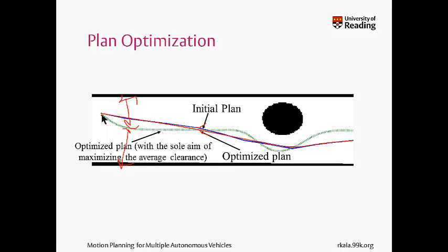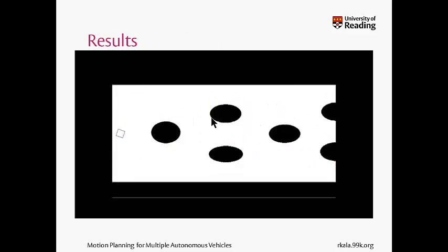So therefore, when the vehicle was here, this road boundary exerted a very big force on it. It exerted a very big force, and quickly it drives to the center. And after that, it's basically always at the center, maximizing clearance, because the forces are very large, so it's always at the center. Of course, this was only used from an analysis point of view. The actual trajectory followed would be this, wherein we won't make one of the forces excessively large.